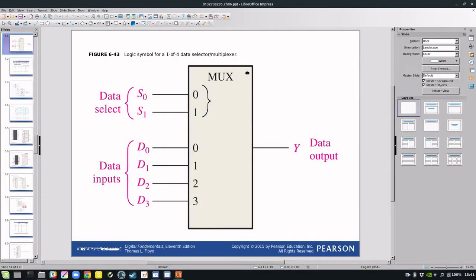Hello and welcome to our tutorial video for Computer Science 330/Physics 306. This will be a short introduction to implementing multiplexer logic on the pink Z1 board. In front of us we have the diagram for a 4 input, 1 output multiplexer with 2 data select lines. We need 2 data select lines in order to pick which data inputs will be connected to the data output.